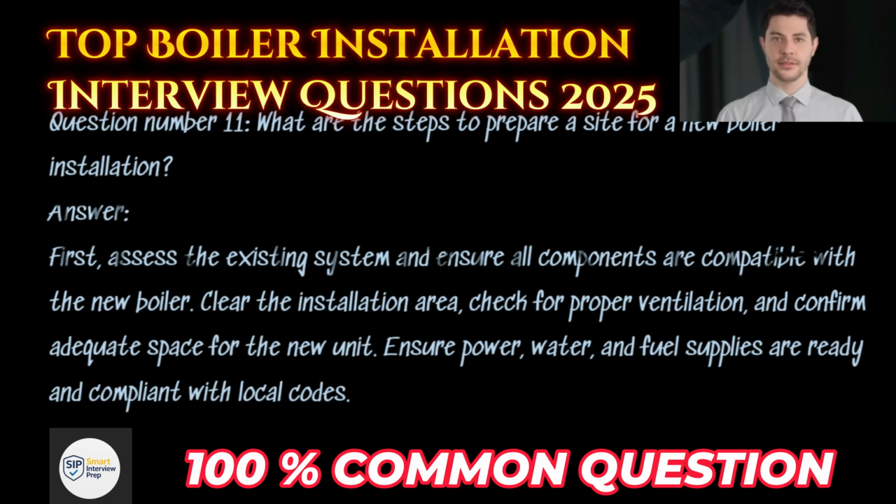Question number 11. What are the steps to prepare a site for a new boiler installation? Answer. First, assess the existing system and ensure all components are compatible with a new boiler. Clear the installation area, check for proper ventilation, and confirm adequate space for the new unit. Ensure power, water, and fuel supplies are ready and compliant with local codes.